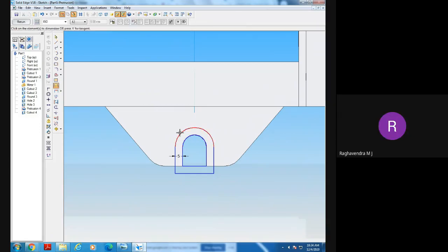Now you can say this is how much? 13. And this width is how much? 26. Are you getting what I am telling? Yes, sir. Remove this, I don't want this, I need only this much. Now go to the return option. Here, end this exactly at this point. Trim this, trim this, this also, this side, this side.